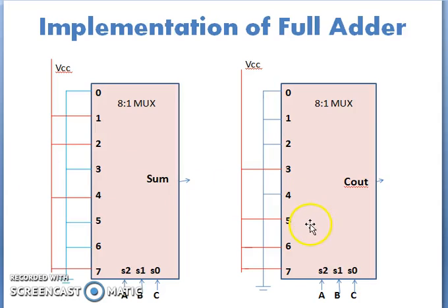So in this figure you come to know, if I apply over here, as we previously applied, that considered example 0, 1, 1, and I want over here 1, as per the behavior of multiplexer, the third input what you applied over here is getting transferred at the output when select line combination is 0, 1, 1. As I want 1 at the output, I must apply logic 1 at this input. Hence, this third input is connected to VCC.